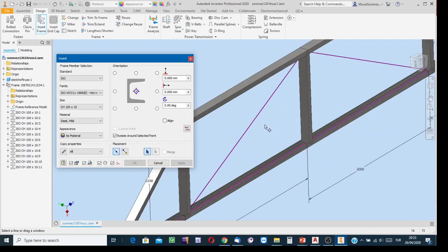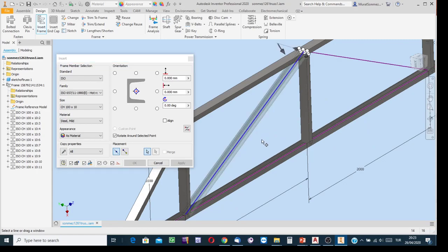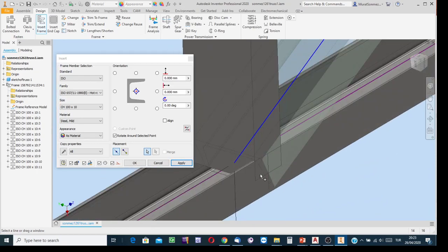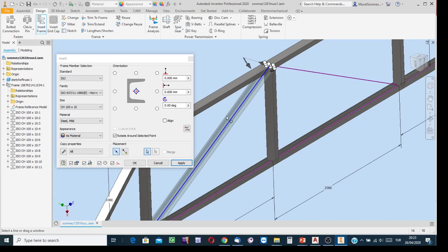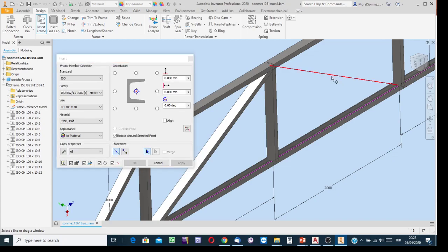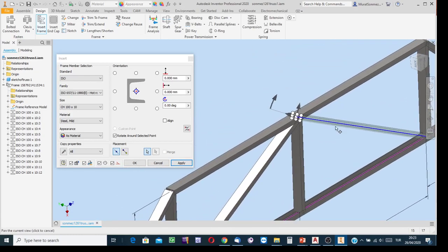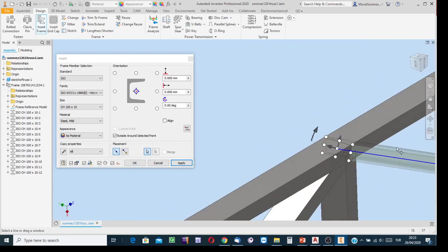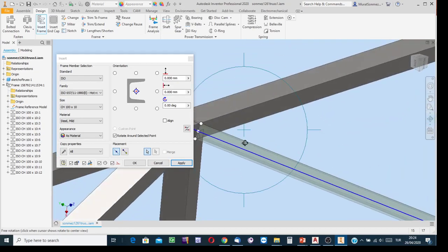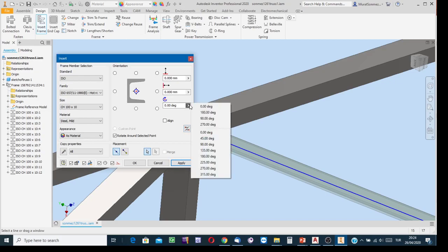Yes, and then the diagonally oriented ones, indicate this one. And then from the simulation, I want to have the flat surface oriented in the up direction. I see from this simulation, the legs are inclined but toward the surface of the earth, so this orientation is better for me. So click the apply button and then say okay, and then indicate the last part of the sketch, and then see the simulation. Well, this member, I see from the simulation, the legs are not toward the down but up direction. So I'm going to rotate this member 180 degrees before saying apply.